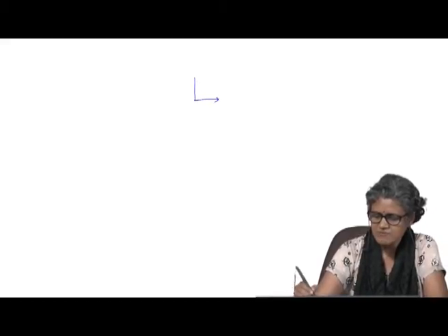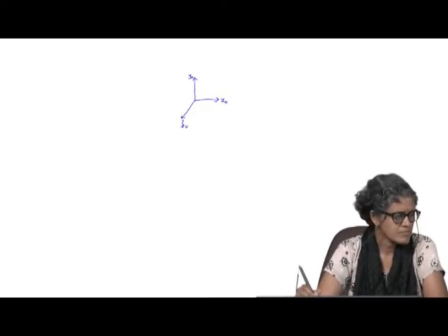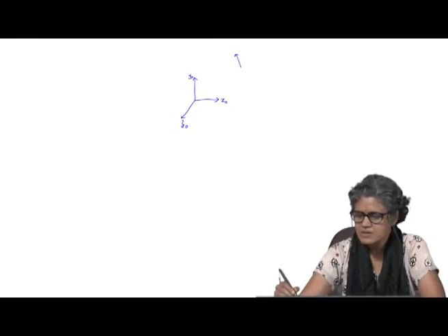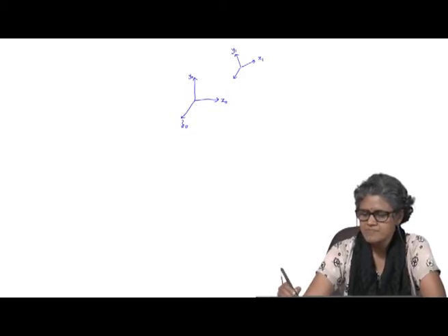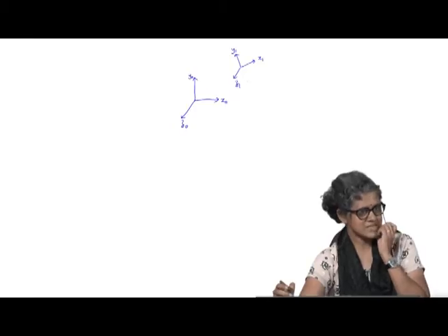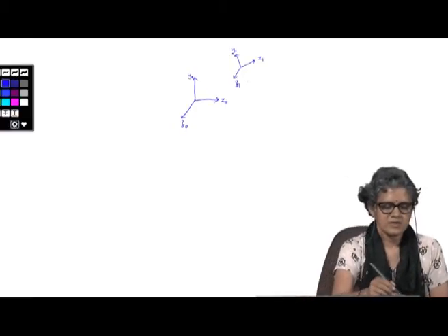So you typically choose, say, coordinate systems attached to the CG of each link. Okay. The chances of the CGs of all the links coinciding is very low, right. So a more general case is when you have a base coordinate system and then you may have another coordinate system which is both rotated as well as translated with respect to the first coordinate system.